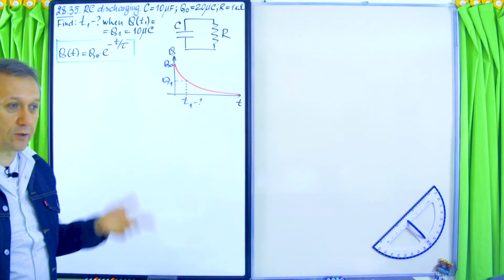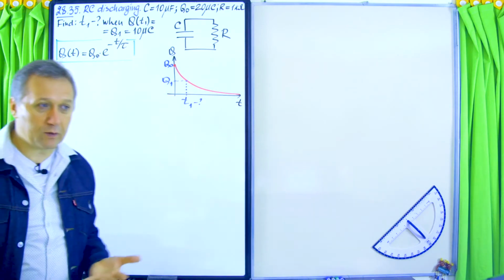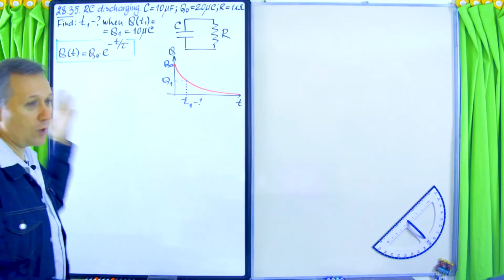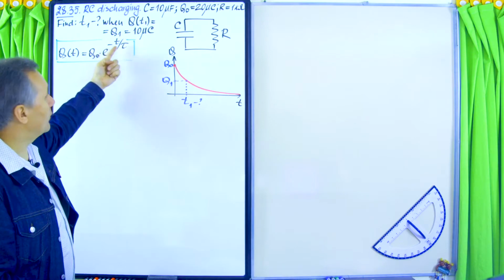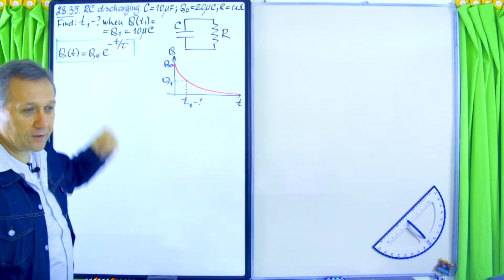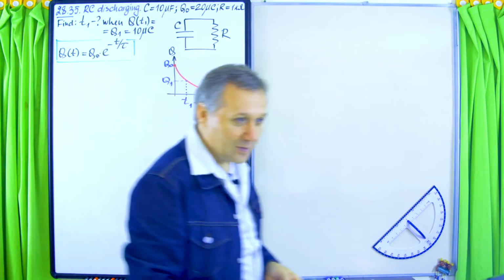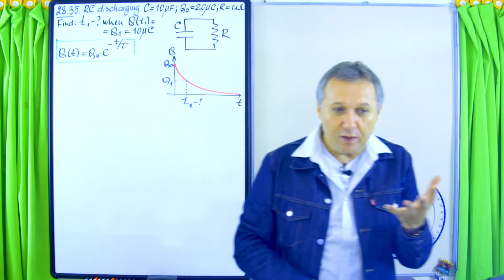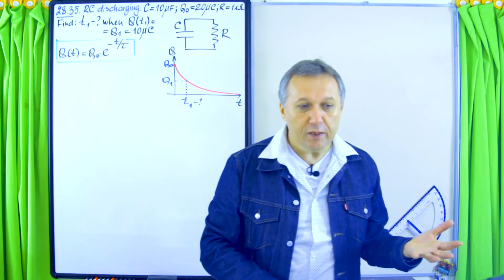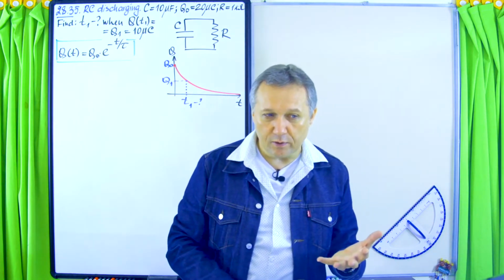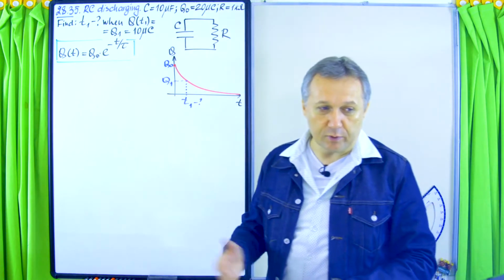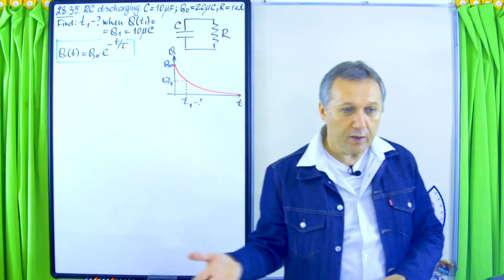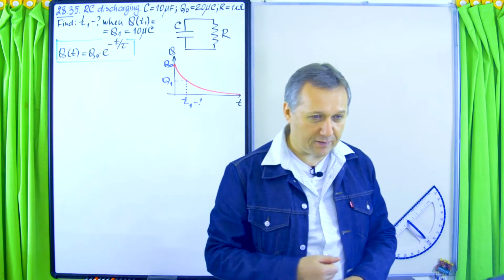But before we start using this equation, what needs to be found? Because right now there are 2 unknowns in this function. We know the time, but we also don't know the RC time constant. But the RC time constant tau is basically an intrinsic parameter if you know everything about the circuit, right? If you build the circuit, you can calculate that easily, because the time constant is just a product of resistance and capacitance.